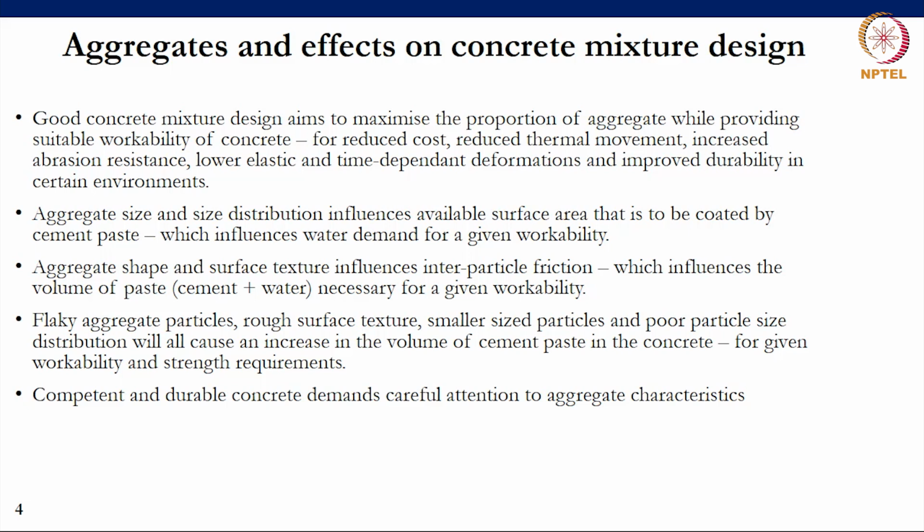So the first principle is that good concrete mixture design aims to maximize the proportion of aggregate, while at the same time providing suitable workability of the concrete. And that is a little bit of an art in achieving the right balance. And the reason we do that is we want to reduce the cost, we want to reduce thermal movements, we want increased abrasion resistance, we want lower elastic and time-dependent deformations, and improved durability in particular environments of the concrete.